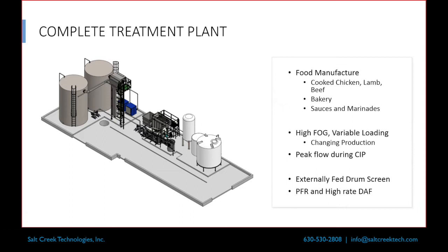So we didn't have a lot of footprint. So we wanted to go with a screen still because they had vegetables and other things coming down the line. So we went with an externally fed rotary drum screen. The reason we did that rather than an internally fed is that they have a built-in overflow. So during those once a week super high peak flows, we're actually allowing that wastewater to overflow and go right